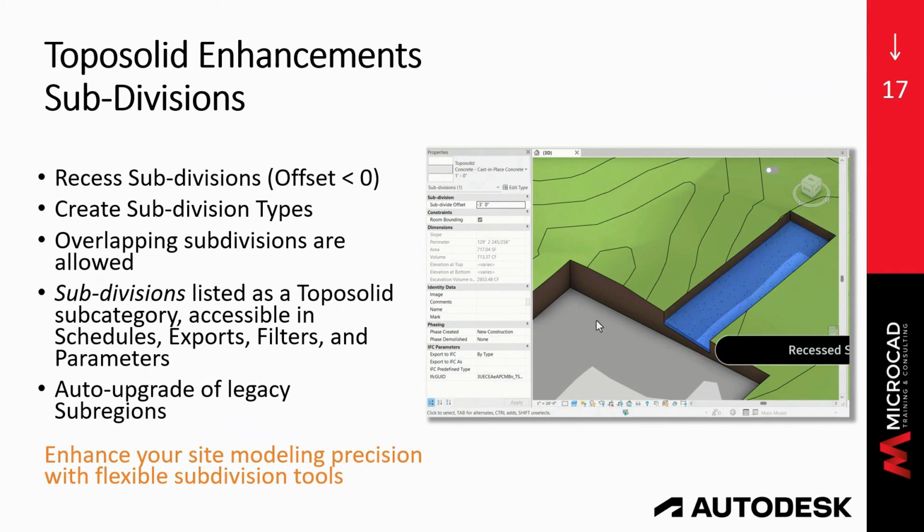And then obviously this is a Revit thing, the geometry limitations in Revit. A layer thickness is limited to a minimum of 1/128th of an inch or 0.8 millimeters, which, I mean, in the building industry, this is minuscule. Okay.